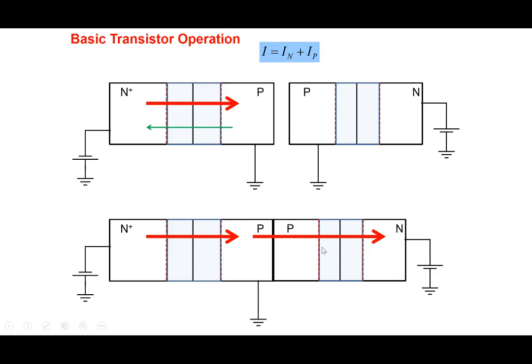So this is very interesting, because note that this is a reverse bias junction. We just said it's a reverse bias junction, and in a reverse bias diode, we expect very little current to flow. But we have to keep in mind, why does very little current flow? Very little current flows because there were very few electrons in the P region. But now that we have connected a forward bias junction, this forward bias junction injects a lot of electrons into the P region, and therefore a lot of current starts to flow here. On the other hand, this component of the current remains as it is. So note that we said that these electrons are about 100 times stronger than this particular part here.